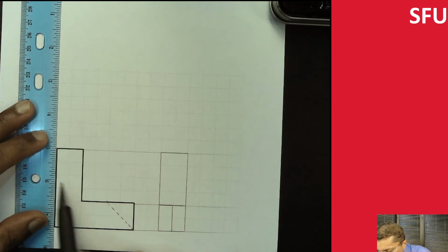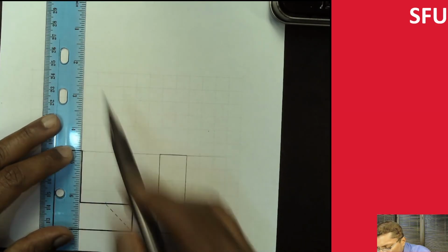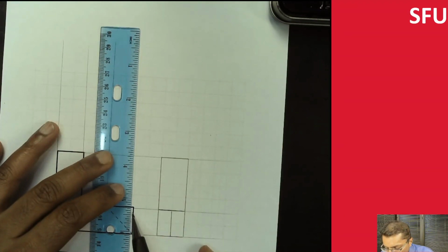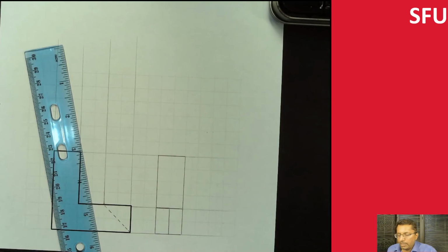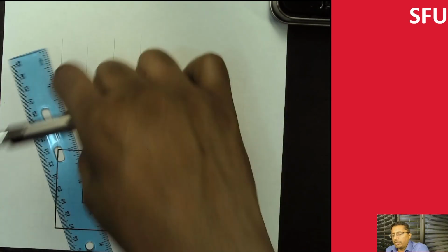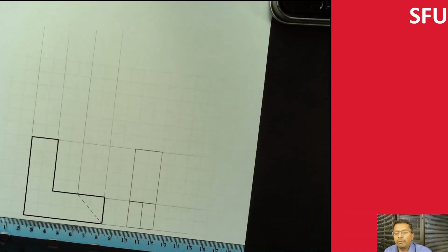So this is fairly easy, right? I'm going to basically just take these lines. So this goes off to infinity, and then this is another feature that's going to show up. So I'm going to take this all the way to infinity, and then there's going to be this feature of interest. I'm going to take a line and take this off to infinity here. So then the question is, how do I actually get or transfer all of these dimensions over here? One way to do it is I can go with a ruler, measure this, and then try to transfer it here. But that gets pretty tedious, particularly if you have more complicated structure.